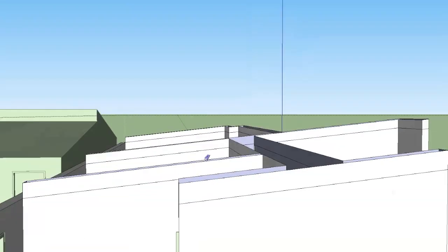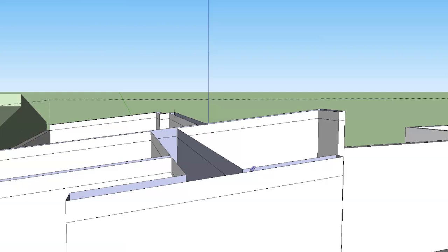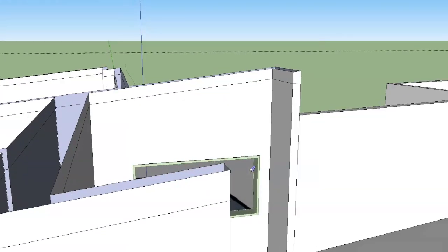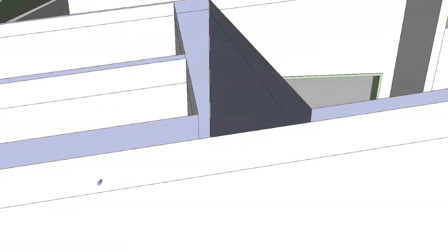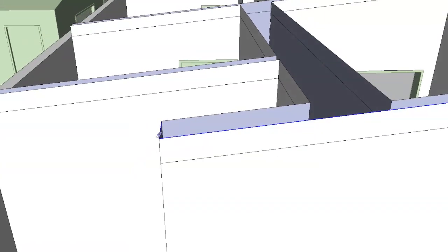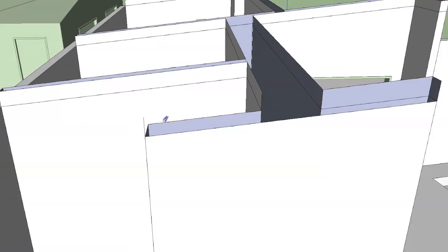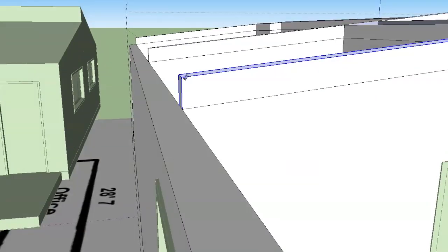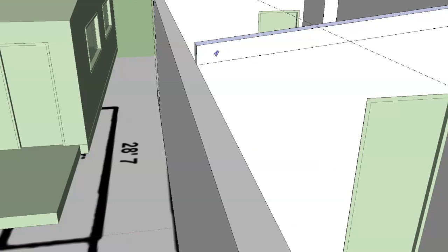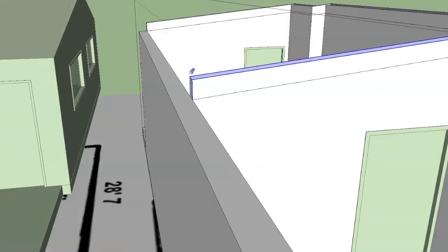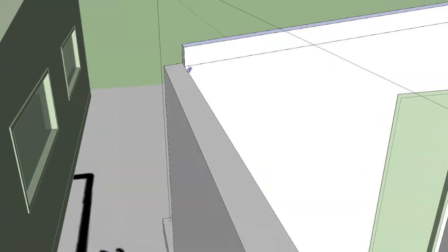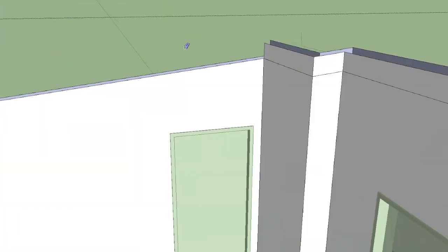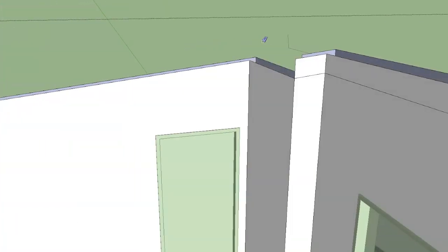So we trim everything down to that first level. So that first level, that's the top of the roof. That's 6 inches above where our walls need to stop. So we're going to take everything down to the bottom line right here. So we're going to get rid of this stuff as well. And you can see right here that our walls are suddenly becoming flush. Our interior walls are becoming flush with our exterior walls, which we know line up with the roof perfectly.